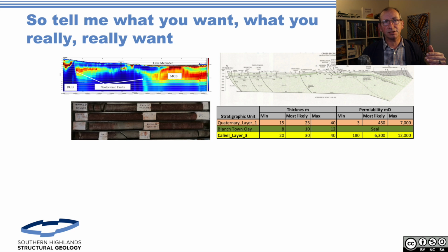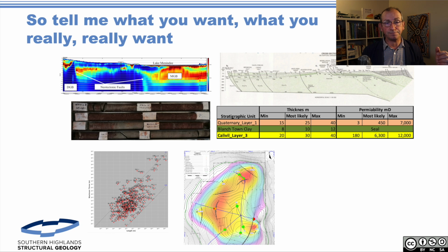Characterize your aquitards. Sure, go and do a whole lot of lab experiments and those sorts of things, but let's actually see sequence stratigraphy and mapping of thicknesses of aquitards. It's not hard. Have a depositional model about why the aquitard is there. Is it there because of whatever? And describe them as distributions as well as having maps.